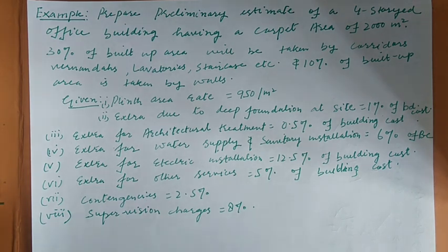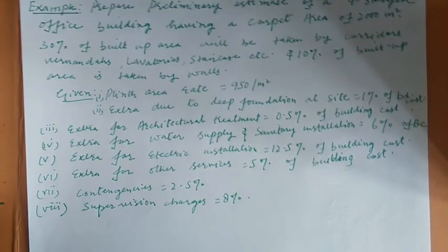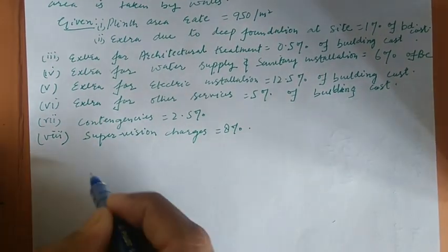Now what is plinth area? I have discussed it in the last lecture. It is the built up area. The only things which need not be considered are the courtyards, the open areas or the cantilever projections. These things are to be excluded from the plinth area. That means the plinth area will consist of all the floors, the internal shafts, and the area of the porches other than the cantilevered. So all these things will be considered in the plinth area. So let us suppose the area of plinth is x. So we will try to solve this like this.